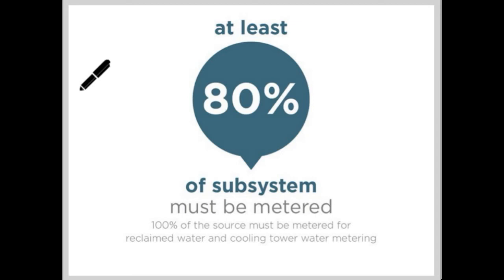Now, for the performance requirements. All meters, including whole building meters, must be recorded at least weekly and used in a regular analysis of time trends. As you would recall, for the prerequisite, recording was only required once a month. For the credit, meters must be calibrated within the manufacturer's recommended interval if the building owner, management organization, or tenant owns the meter.